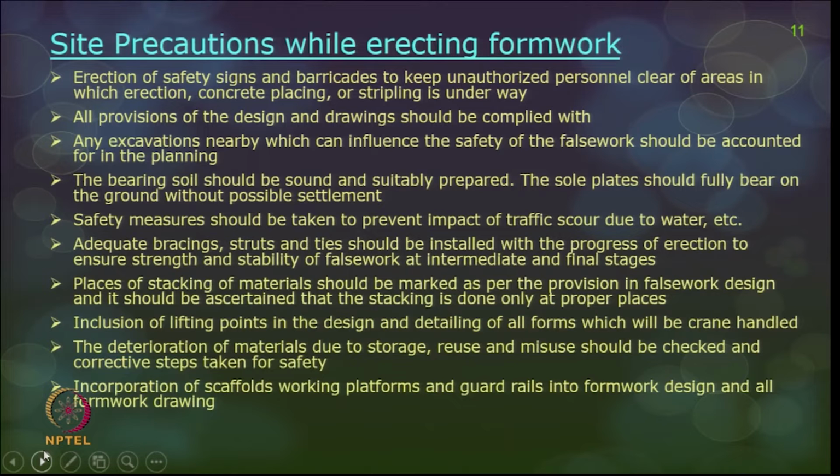Safety measures should be taken to prevent the impact of water, traffic, scour due to water and so on, and adequate bracing, struts, and ties should be installed with the progress of execution in order to maintain the strength and stability of the formwork at intermediate and final stages.